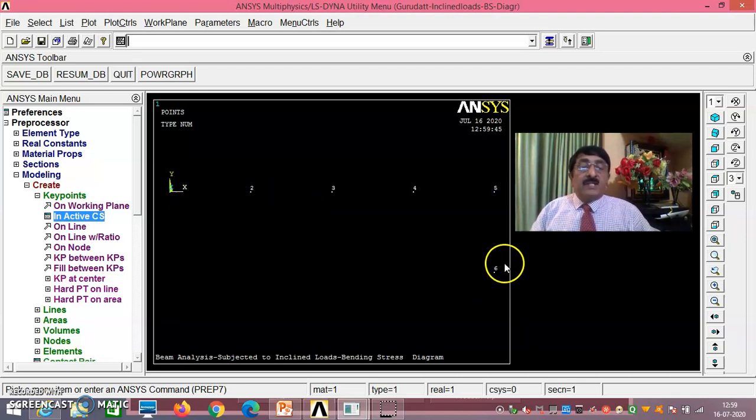The significance of this, as I told you, is just for the beam to rotate by 90 degrees, because it would not have been aligned. For orientation of the beam, this point is necessary, which I'll be explaining to you later on. Right now, don't worry, there is one point created. It can be any distance, but you have to create one point here. I have taken -1. It can be -2 or -3, but just to fit in the screen, I have taken -1.